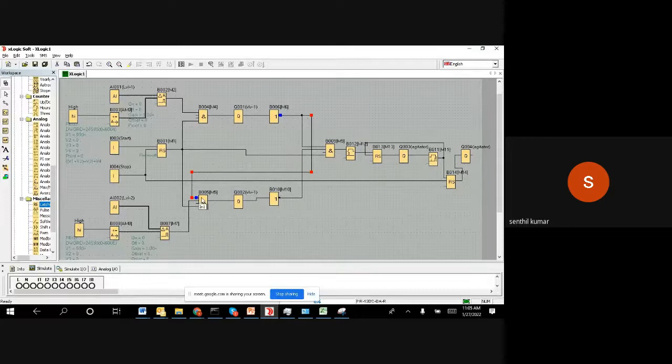So okay, let us check this Q. By the time when it is on, the tank level is going to be 1000 because now only you are opening. Since it is 1000, this also will be 1. And the other leg, the initial start is there, so that's why this is also 1. So now the 3 legs are 1. Then what will happen? Your second valve will open.